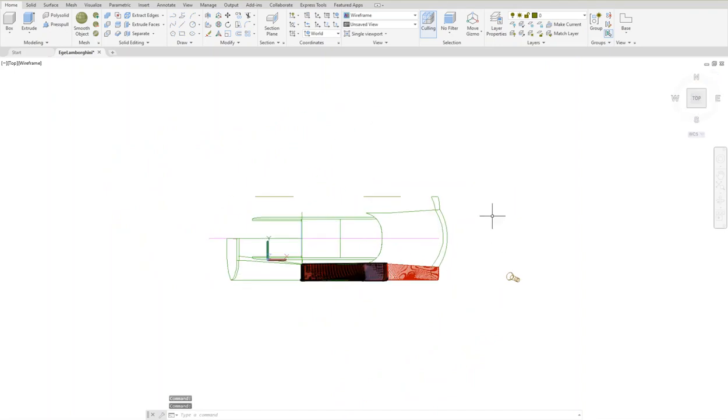One of the things I want to demonstrate today is that once you create a surface of the car, there is also the possibility to mirror that surface on the other side, so that you don't have to create it twice. The only condition for that is that you have to have a perfectly drawn mirror line, and we have that mirror line already created here at the right center. The command is mirror, and I'm going to simply type it. It's an easy command to remember and to apply.